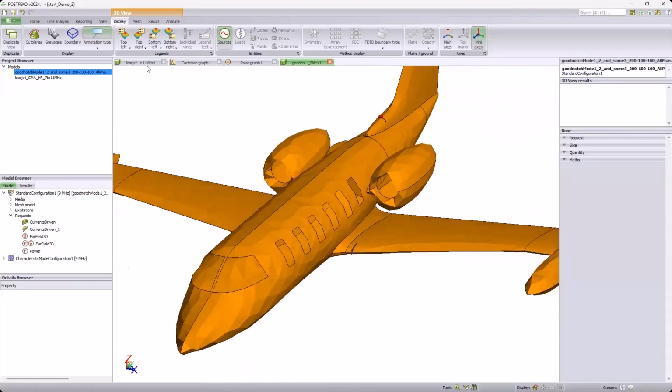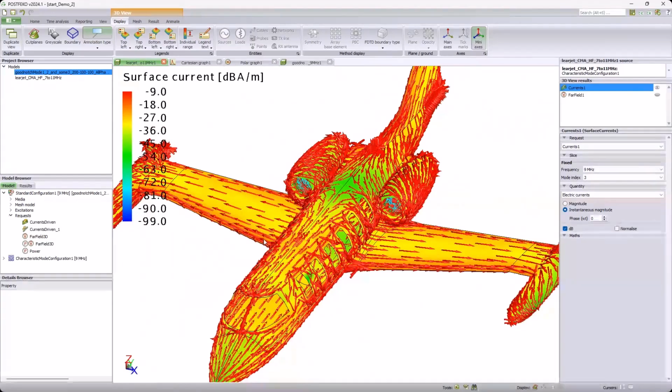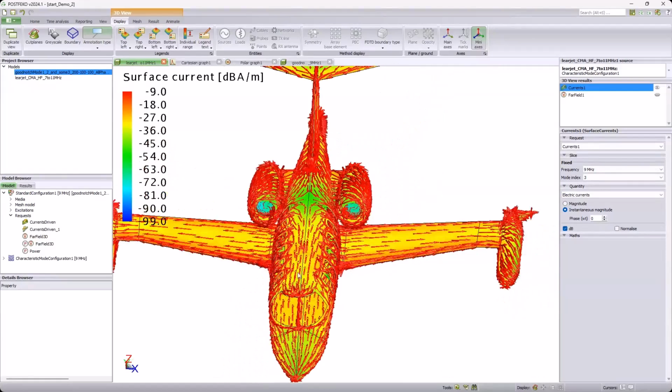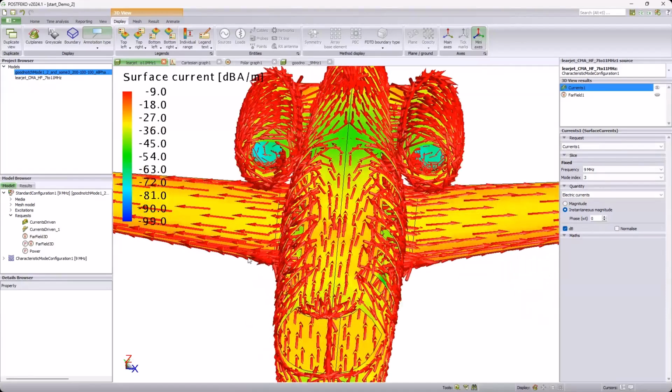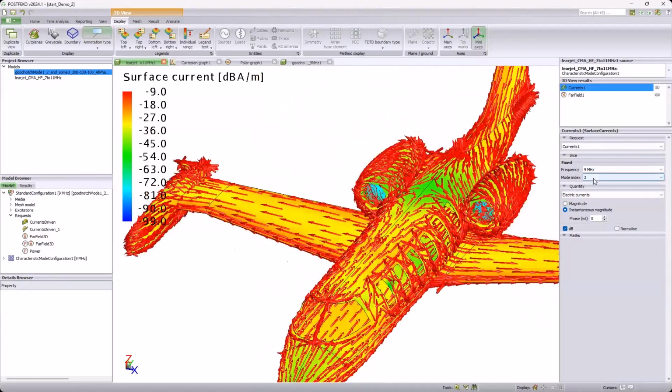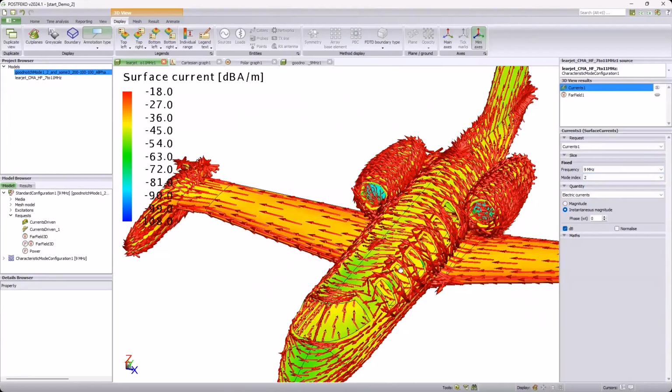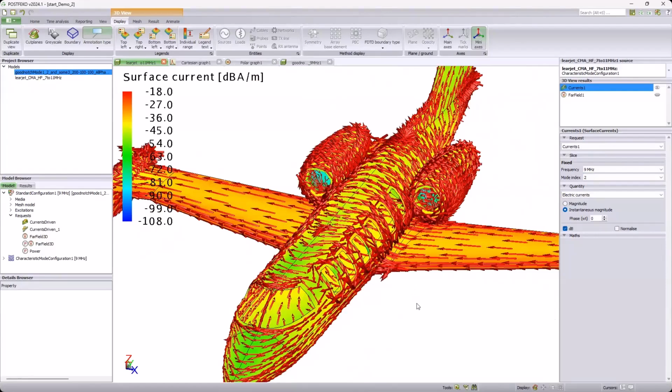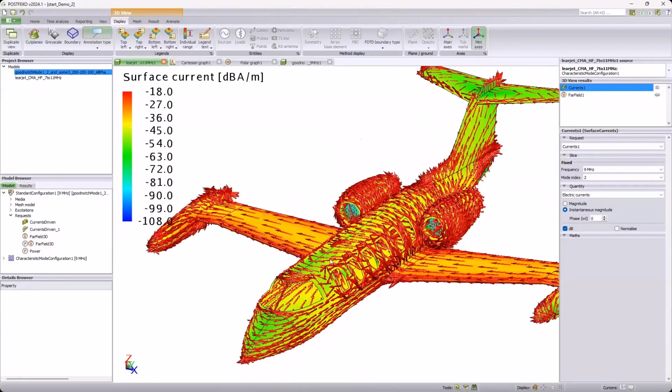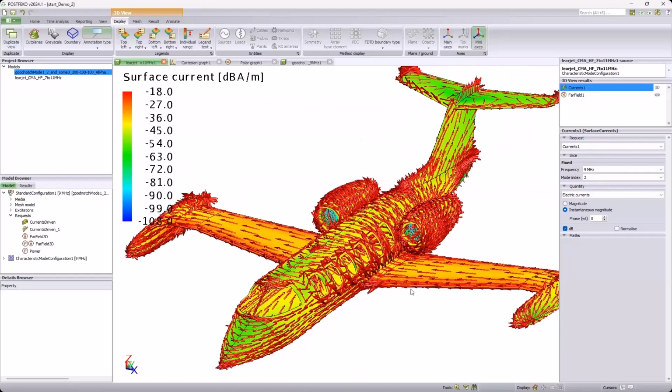Now, depending on the orientation of these currents, we can use different phasings on these antennas to achieve the different modes. So for example, if I were to phase the 2 antennas here on the sides of the fuselage connected to the wing out of phase, I would probably excite this mode 3. If I were to excite them in phase, I could excite mode 2 with the currents flowing in phase. It's also possible to tweak those phases and have a different combination of phases where they are either in phase or slightly out of phase to achieve a combination of the modes.